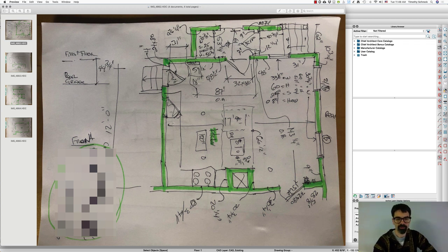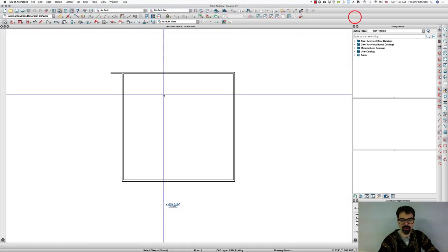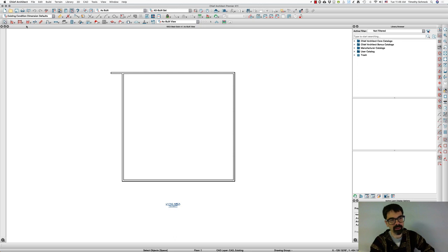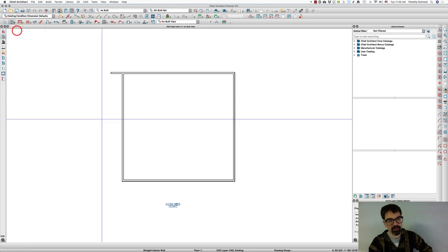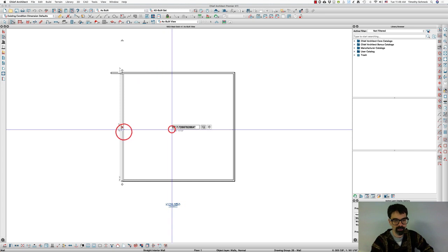You'll notice I like to ask for overall dimensions, so 17.1 by 143.25. This is a great reason why I put in my template, my as-built dimensions have primary and secondary numbers turned on. One dimension in one direction is shown in feet and inches. The next is shown as inches. So let's show that. I've drawn the basic outline here. So I'm going to give 17'1".